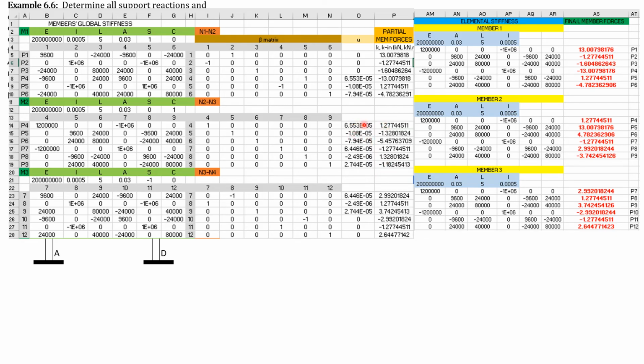These are the displacements for member 2 and 3, because it is 4, 5, 6, 7, 8. B and C have global displacements. These are the results, global displacements here. And this will be automatically generated here after the overall stiffness matrix, where we can find the global stiffness matrix. And member 2 has fixed forces. For axial, it's none, so the axial value is the same. But for shear, there was.